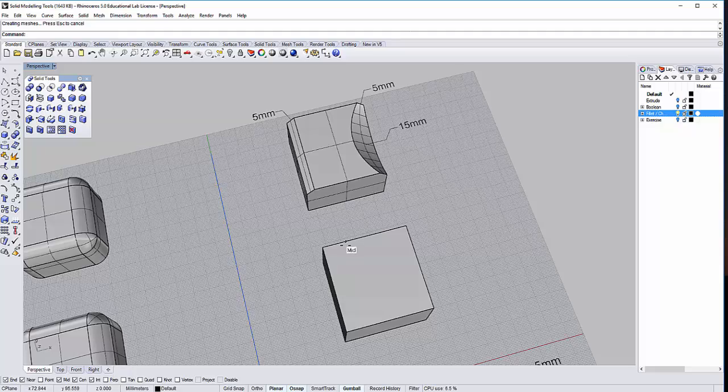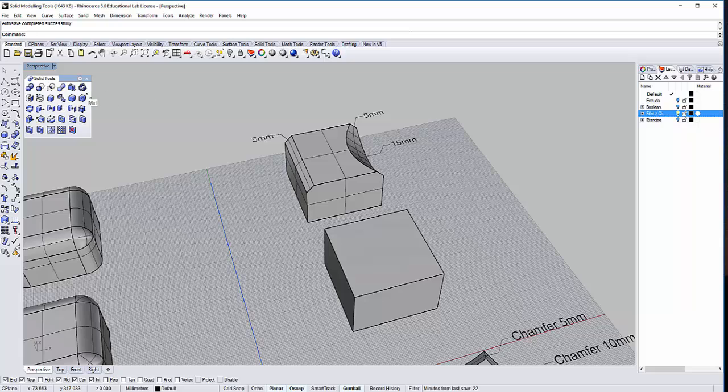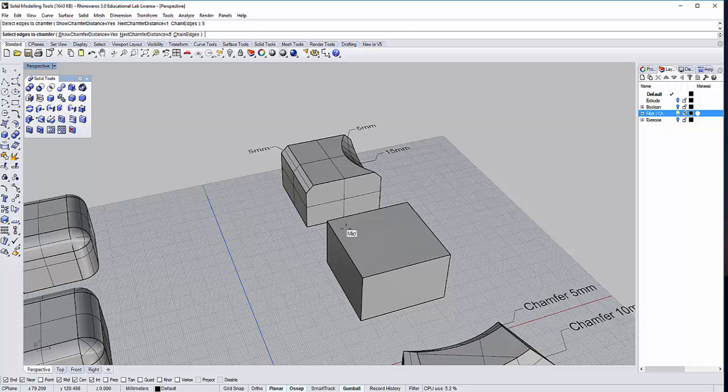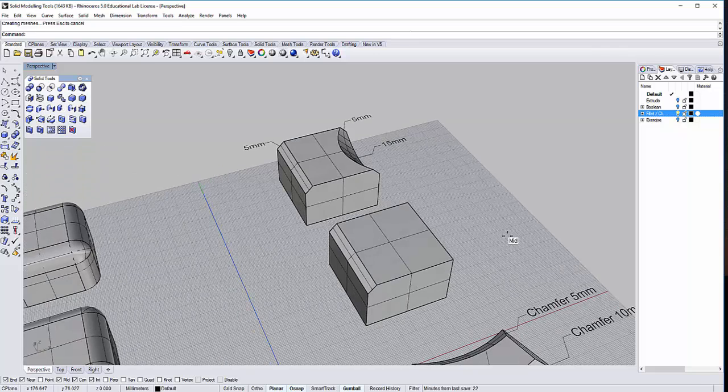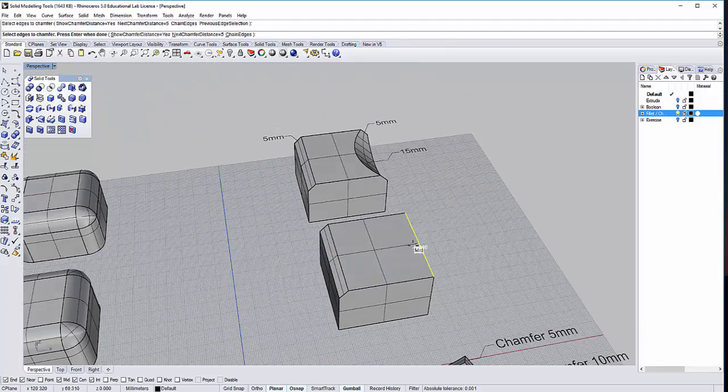Okay, right now let's say for example we want to do chamfer, which is on this side here. You press the chamfer. I want a chamfer 5 input. Okay, now it says 5. Which edge is this? This is this. Press enter. It will cut. Alright. Let's say for example I want a so-called chamfer of 2 dimensions. Yeah. I can press enter again.